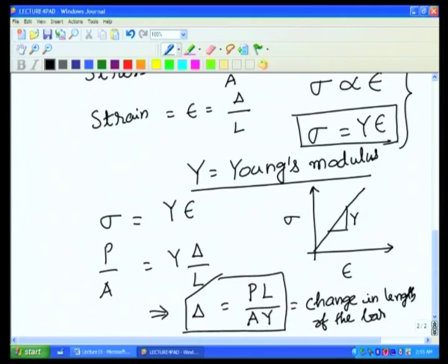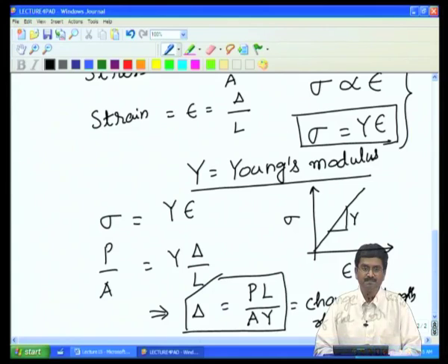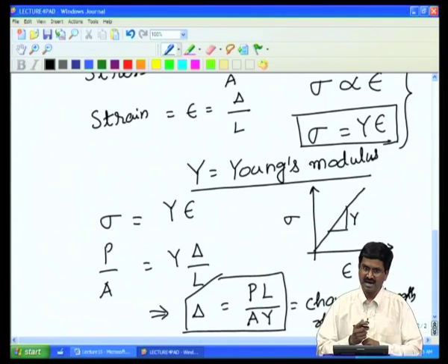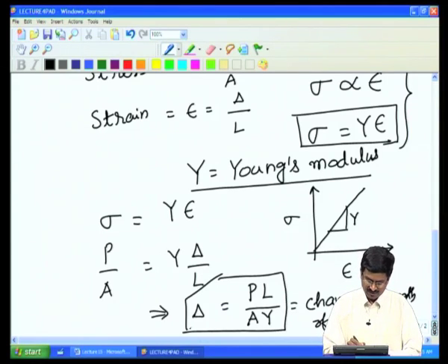As we will see, as we consider more complicated elastic bodies, the bar, by the way, is the simplest elastic body that one can imagine. It can only axially stretch and contract. If we take more complicated elastic bodies, our principle is still going to be the same. We use static equilibrium, so that all forces are balanced, and later on we will also have to balance what are called moments. After that, we use our definition of stress and strain, and then relate stress and strain based on the property of the material, which is Young's modulus, and we can compute the elastic deflection as shown here.